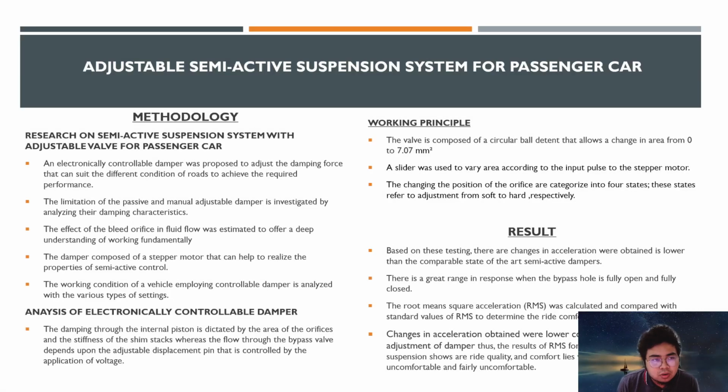I will present the third journal, which is the adjustable semi-active suspension system for passenger car. The methodology for this journal is research on a semi-active suspension system with adjustable valve for passenger car. An electronically controllable damper was proposed to adjust the damping force to suit different road conditions to achieve the required performance.